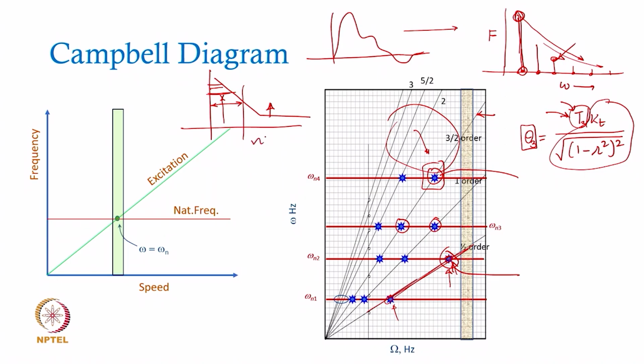Ultimately, these are number of cycles. Now, if the stress reversal is happening at 20 hertz and if the stress reversals are taking place at 100 hertz, which one will be generating more number of cycles? The ones with higher frequencies. I am not bringing in the amplitude here at the moment, but the point is that the excitation components at higher frequencies are also not to be forgotten or ignored, because they consume in a given period of time more number of stress reversals or cycles.